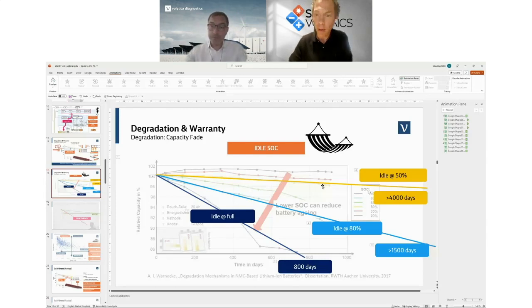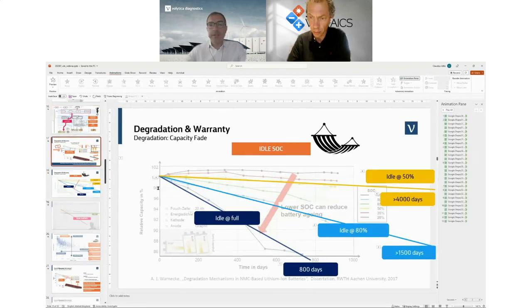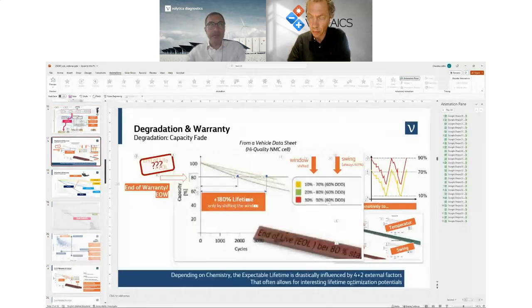Right. Okay, another question. It's about the depth of discharge. Is the DoD problem solved with just using the SOC between 10 and 90%? The short answer is it depends on the cells you use, because I'm again just picking examples here. Sometimes battery cells are very susceptible to that range.